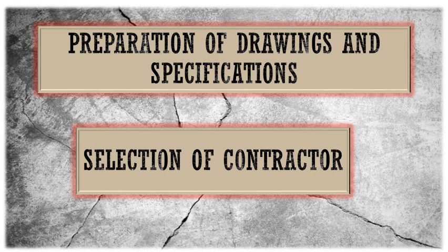Once the concrete condition survey and diagnosis is completed, and the selection of the most appropriate concrete repair principles and methods is made, then the detailed project specification-based quantities must be prepared.